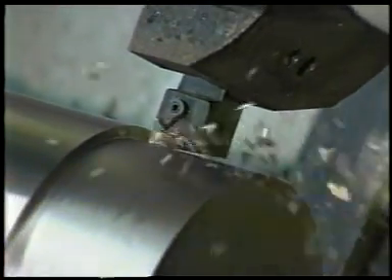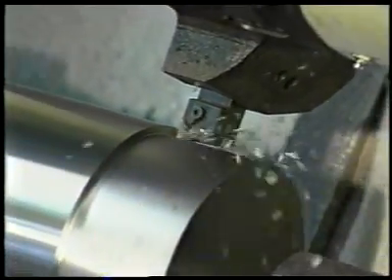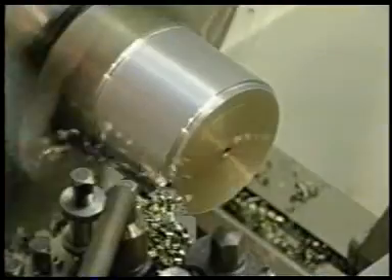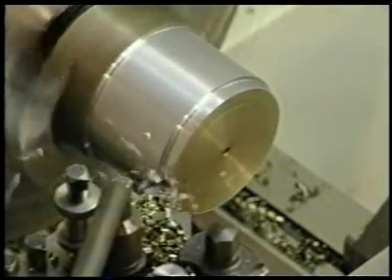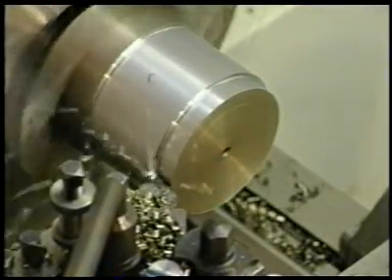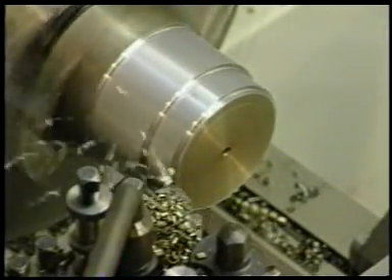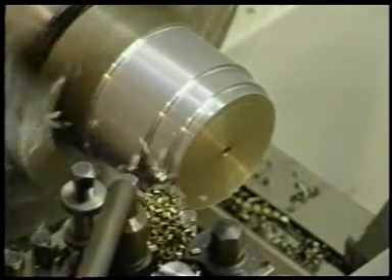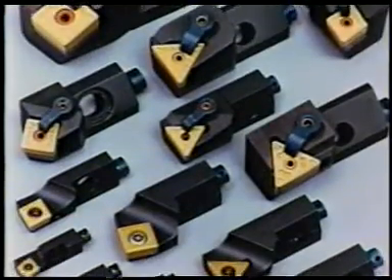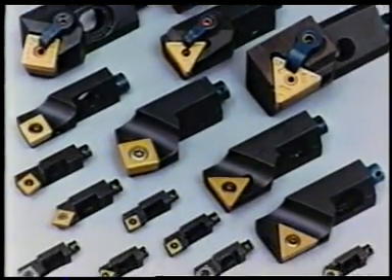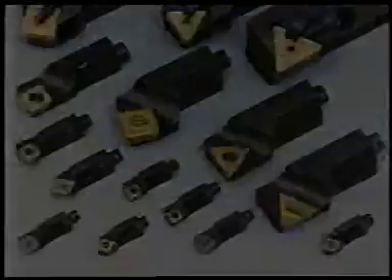If the effective cutting edge length is less than the depth of cut, a larger insert should be selected or the depth of cut reduced. Light cuts can be done with a smaller insert, but too small an insert might require 2 passes to be made instead of 1, which is uneconomical. For even the smallest jobs, there are appropriately sized inserts, tool holders, and boring bars.